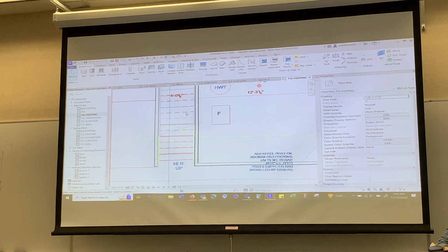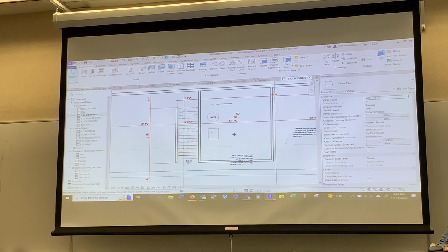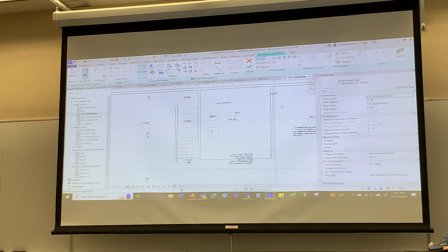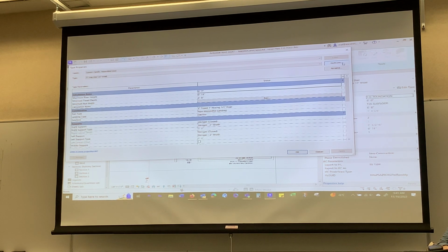Now, the stair tool is pretty unforgiving. If you screw it up, it's one of those things you pretty much have to start over each time, which isn't a bad idea. I'm bound to screw it up a couple times here because it's weird. So I'm in Architecture, come over to the stair tool, it's right beside the ramp. It's underneath View for me. I click on my stair tool. It's a sketch mode thing, so you know right away it's gonna be weird. We only get this one type, so the first thing I'm gonna do is modify it, and I'm gonna duplicate it right off the bat.